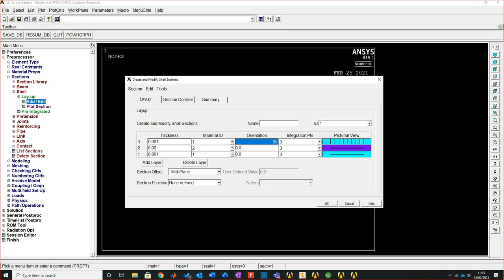If you know the relationship between carbon and Kevlar, there's no reason why you couldn't have a carbon material, a Kevlar material with a sandwich in the middle, and then repeat the same process on the other side. There's so much you can do with this. And this is why a lot of researchers use it, because you can actually code some of these operations. It allows you to manipulate what the geometry is doing, so you can get an even more accurate representation. This is also another way that you could look at the relationship of polymers when they're interfacing through fuse deposition. Anything like that, that's what this will do.